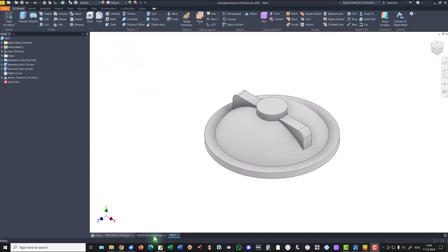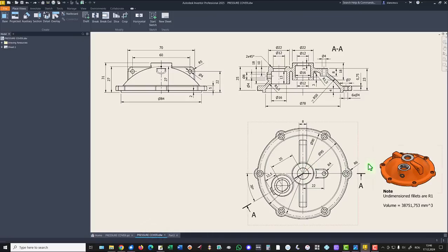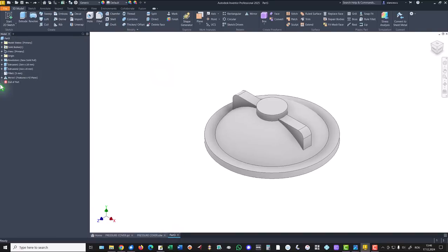And then we create the other cylinder, this one, placed in a plane at 30 degrees from this axis. Or if I consider this plane, which is the plane of the ribs, XY, we measure here 90 plus 30 degrees. Let's create that plane firstly.